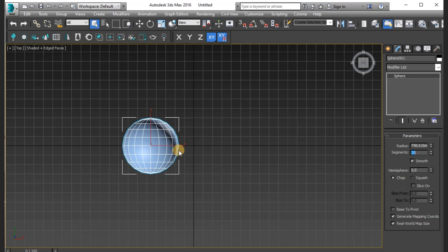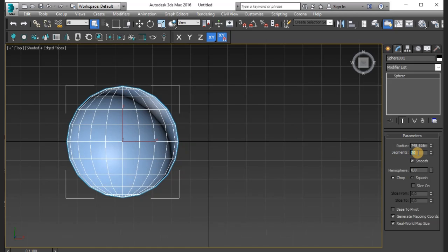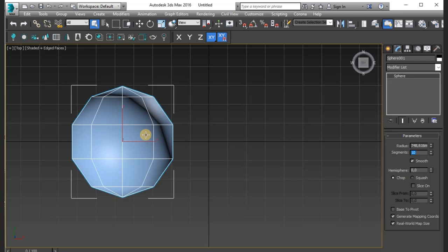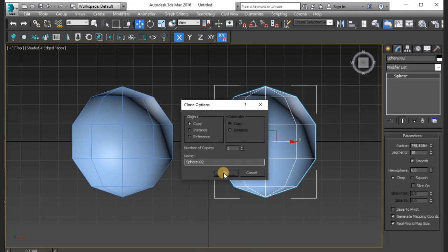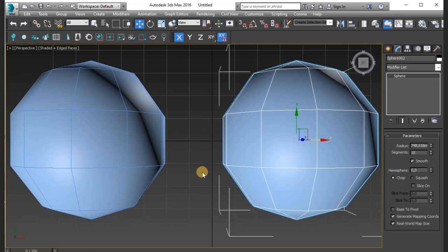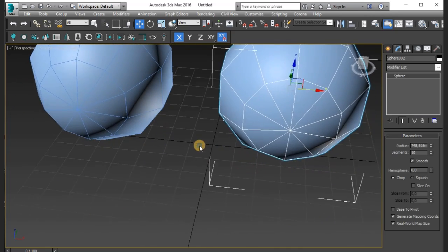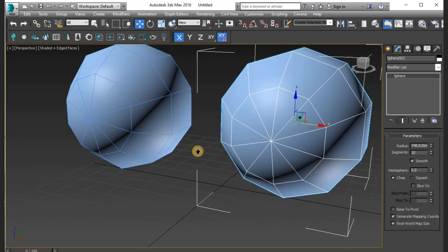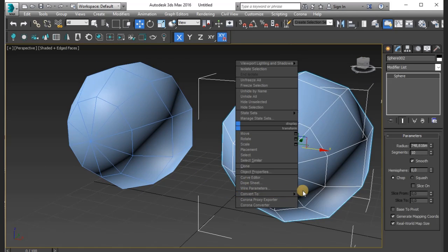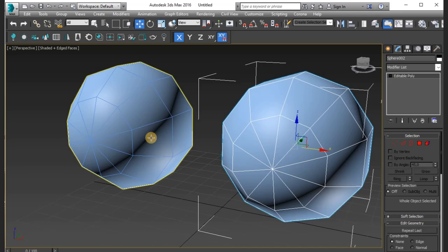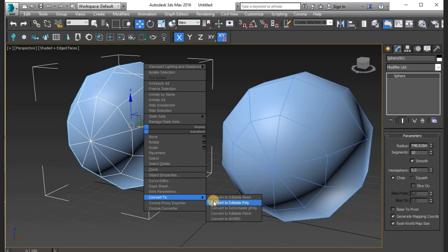Now, select the sub-objects of the editable objects in the viewport and then press the Delete key to delete the selected face or polygon sub-objects. Note that you need to position the objects in such a way that the holes face each other as shown. Next, select one of the objects and choose the Connect tool from the Object Type rollout in the Compound Objects.